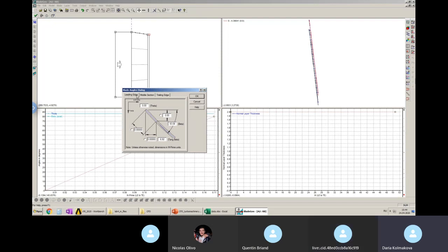So what can we see here? We can see the tabs for the leading edge and for the trailing edge of the blade. For the leading edge and trailing edge, we need to set up only one parameter, which is beta 1. But in this case, beta is set up from the X, whereas in Russian practice, in your calculation, we calculated all the angles from the front of the cascades, or from the leading edge line. That means we need to set up not beta itself, but 90 degrees minus beta.